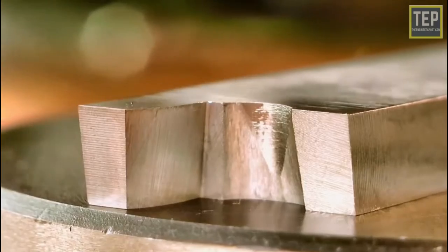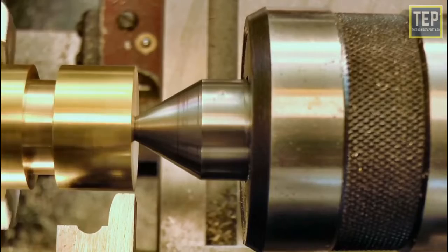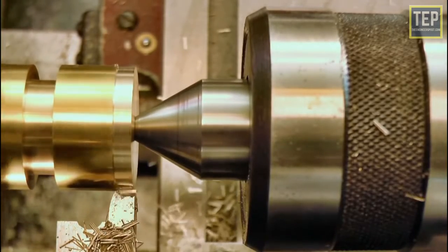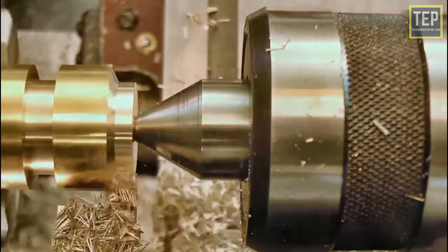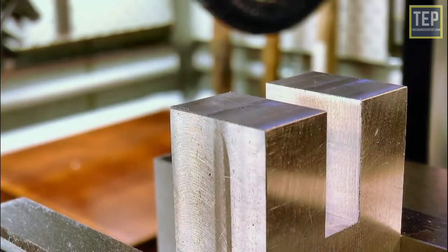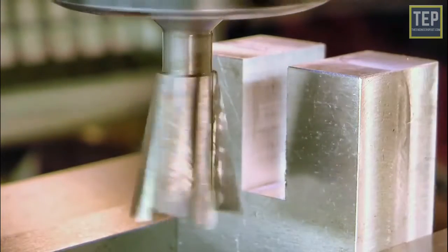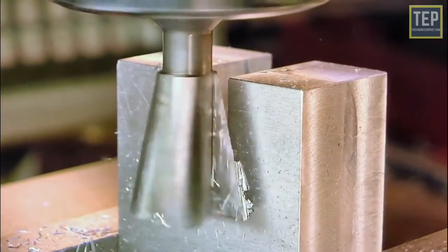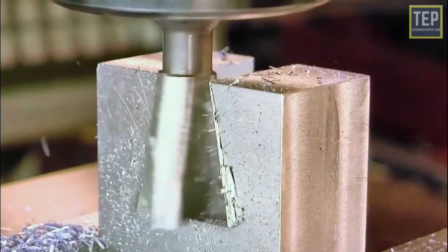Forming tool. An ordinary lathe turning tool may serve the purpose where a copying attachment is used to reproduce the form of a template. These tools have their cutting edges ground to the shape of the groove, undercut, or thread to be cut. Flat dovetail forming tools have a wider cutting edge corresponding to the shape desired. The dovetail end of the tool is fitted in a special tool holder. No front rake is provided, but sufficient front clearance angle is given. Regrinding is always done on the top face of the tool, which does not alter the form of the tool.